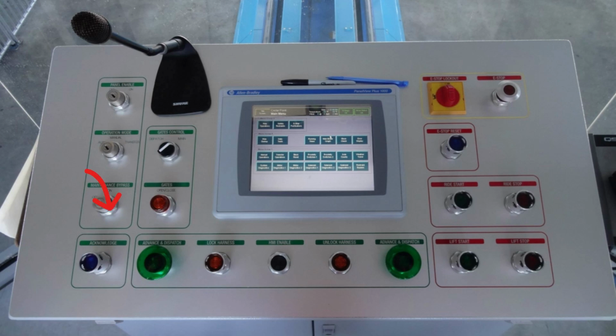This is the maintenance bypass switch. If the ride needs maintenance done to it, they will insert the key and turn this switch so that it will turn the ride into maintenance mode. Gate switch. So if the ride is in manual, this switch will enable them to open and close the gates. This is the operation mode switch. Typically it's in automatic mode, but if the ride has to block test or put the trains away, it'll switch over to manual mode so that it will stop the train on block sections and it has to get permission from the operator themselves to leave that block section.